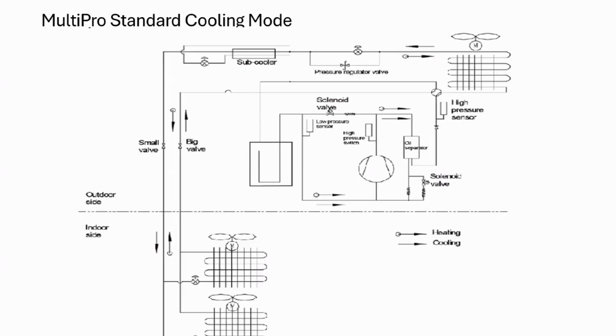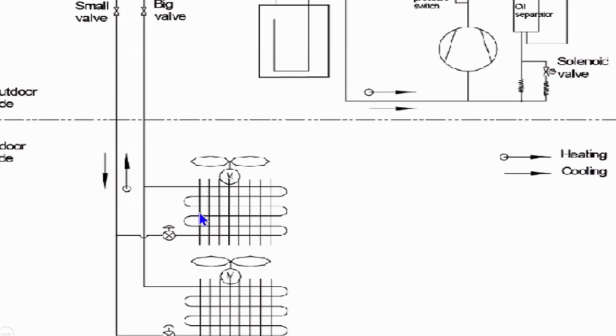So what I'm getting at here is that's when the service tool or the GREE controllers, we're going to talk about that more. I'm just trying to prep you guys for where we're going with all this. Each one of these coils has an inlet and an outlet temperature thermistor on that coil. When you have the service tool hooked up, not only can you see the temperature of the outlet of that coil, but also the inlet of that coil right after your metering device. So if you're in cooling mode, that ought to be flashing off pretty good, and we ought to have a fairly cold input to that coil, right?